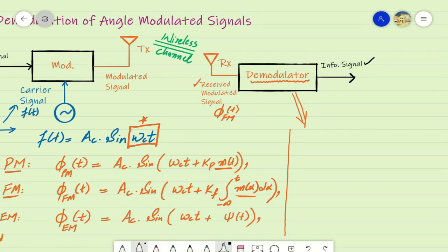The information in such frequency modulated signals resides in the instantaneous frequency. Therefore, a frequency selective system with a transfer function which can discriminate among different frequencies over the band of a frequency modulated signal can help in obtaining an output proportional to the instantaneous frequency, as the changes in instantaneous frequency represent the information signal. Therefore, detecting the instantaneous frequency translates into the detection of the information signal.